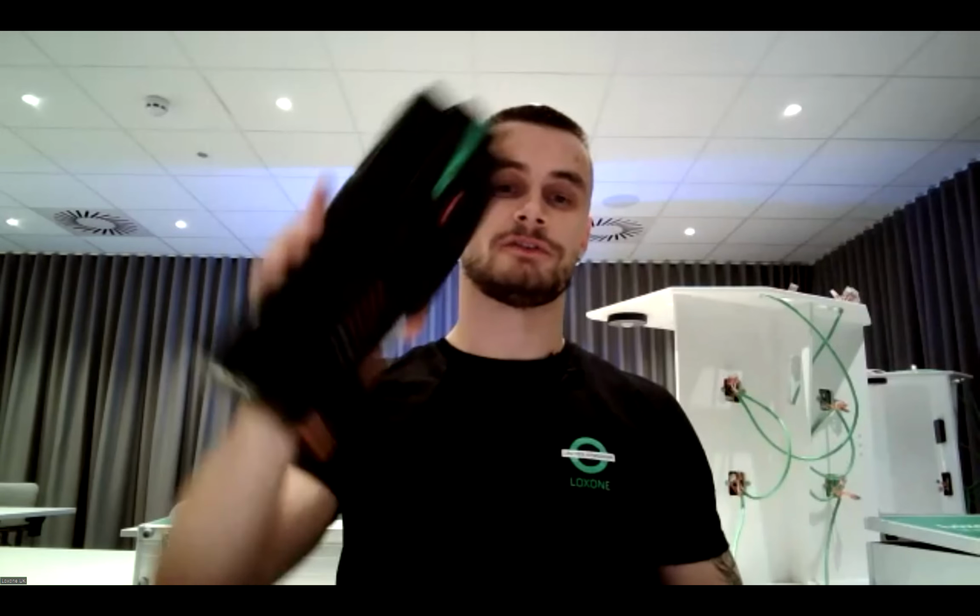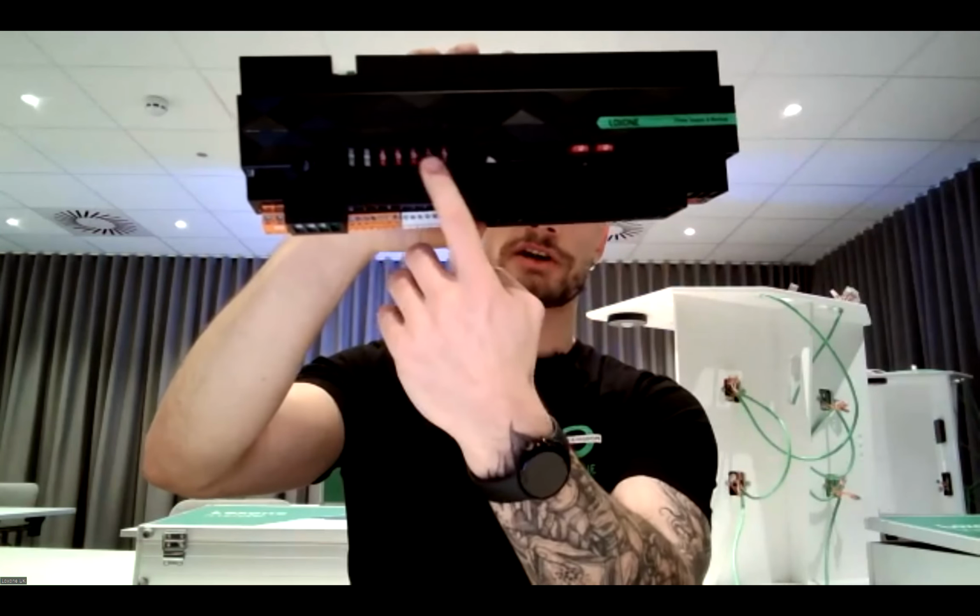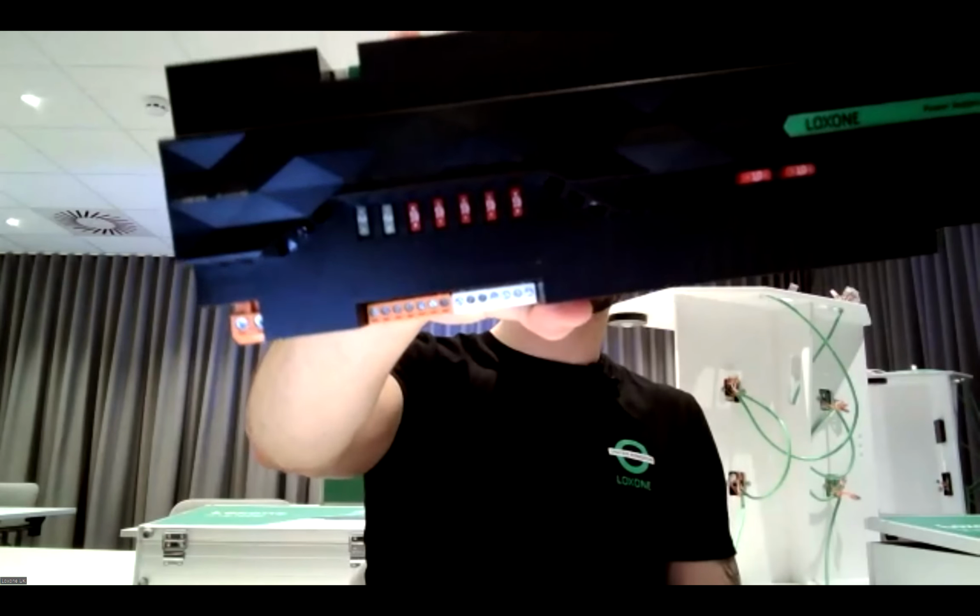So we wanted to make sure, okay, this is our showroom space. This has to be the best of the best. It has to show to every single customer that walks in what is possible. And that is why we spec'd it to 100% load. However, this is going to be more than adequate. And again, the blade fuse on top we do not require, because every single channel is going to be fused in here already. And that should be more than enough.